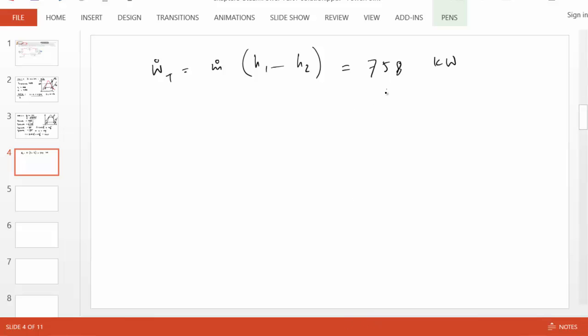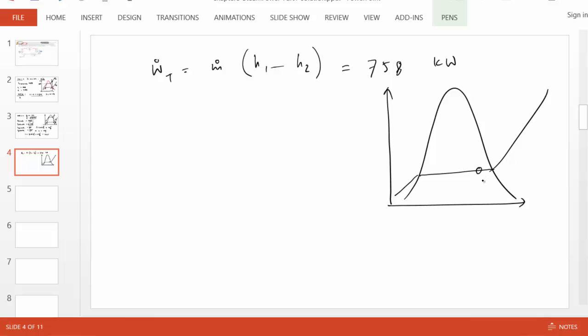Okay, now let's get the condenser exit state. Recall, this was our state 2, and after that the steam is cooled to state 3, which is a saturated liquid. So for state 3, we know in an ideal Rankine cycle there is no pressure drop. So pressure is the same as pressure 2, which is 100 kPa, and we know the quality because it's saturated. At state 3, it's the F state. So that's an important thing to remember: X equals 0 for the F state and X equals 1 for the G state.